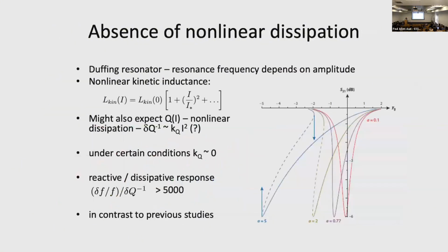This can all be described using a nonlinear Duffing type resonator model, where the kinetic inductance is current dependent. It has an I squared nonlinear term. And that's all been understood for quite some time.